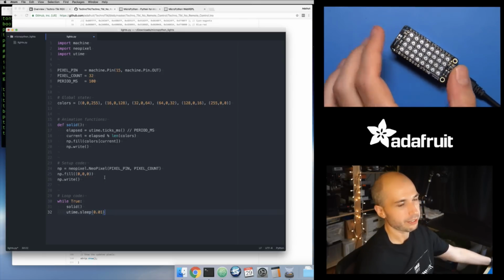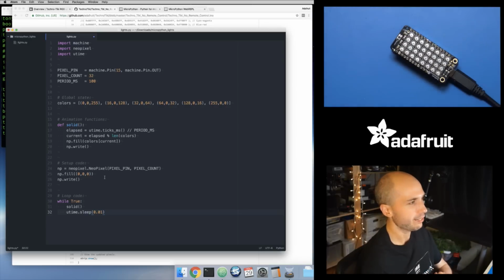But on the ESP8266, it actually needs some time slices to give to the Wi-Fi radio and things like that. And so the sleep function is what you need to call to basically say, okay, in my main loop, I'm done running my code. Go just delay for 10 seconds. And while it's delaying, it's actually doing things in the background. So it's usually smart in your loop to have a small bit of delay inside of your loop.